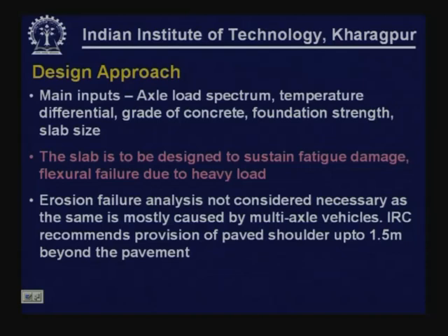The design approach consists of the main inputs: the axle load spectrum. We have to have information on the axle load spectrum, the temperature differential, the grade of concrete we are going to use, the foundation strength, and the dimensions of the slab, which can be obtained after fixing the joint spacing.